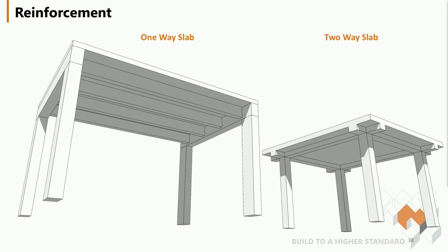For comparison, a two-way slab is where the point load would transfer its load in both directions, as opposed to the single direction of the one-way slab. A two-way slab would need to have support on all four sides, beams or walls, while a one-way slab requires supports only on two of the sides perpendicular to the joists.